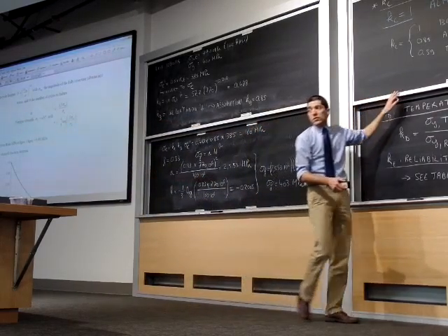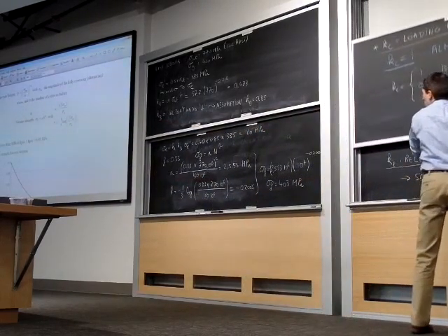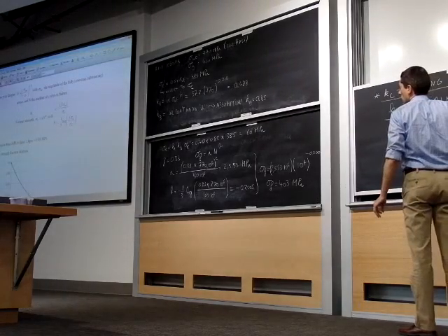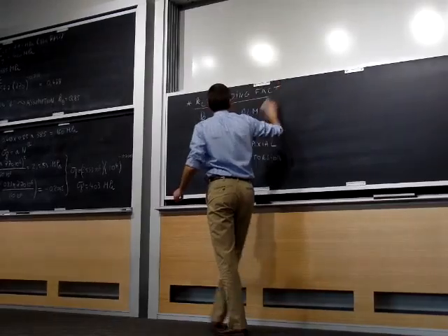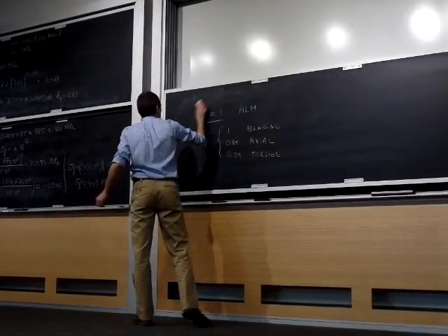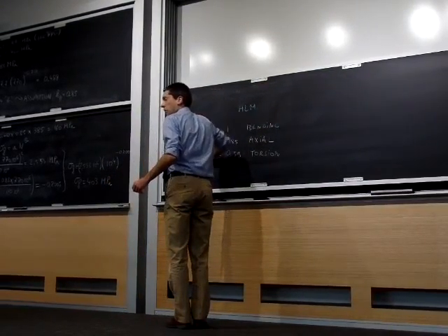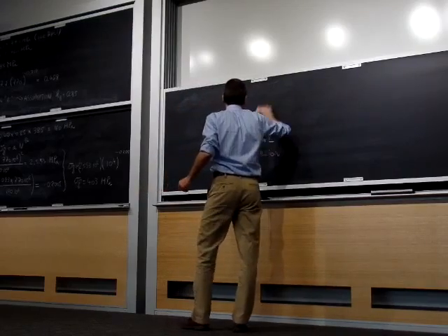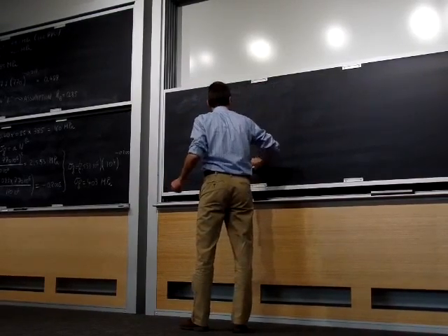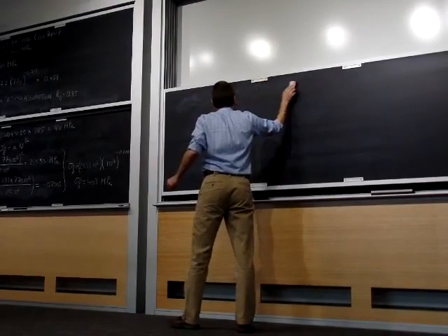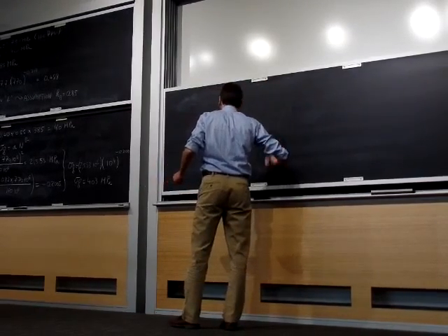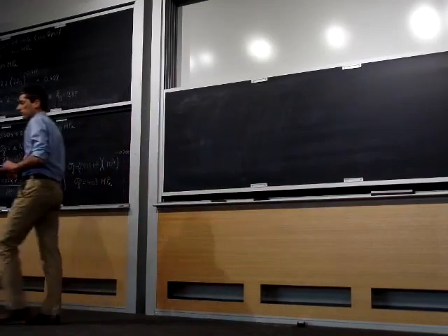No, we always use the ultimate tensile strength even for a ductile material. We're actually currently working with a ductile material, right? We're mostly going to work with steels, and steels are by and large ductile materials unless they become exotic alloys. So you just use the sigma ut as it is in the formulas.